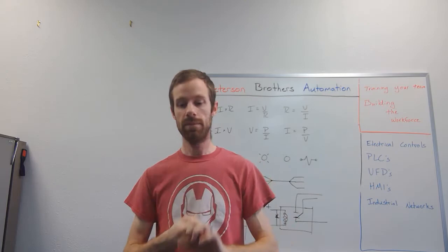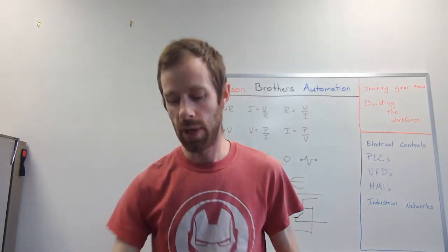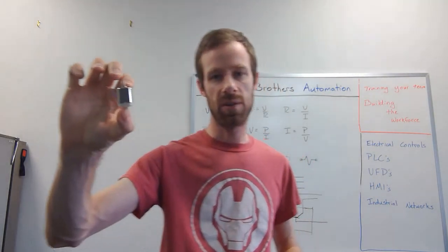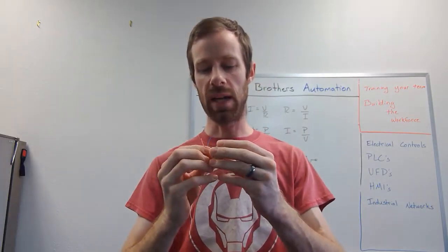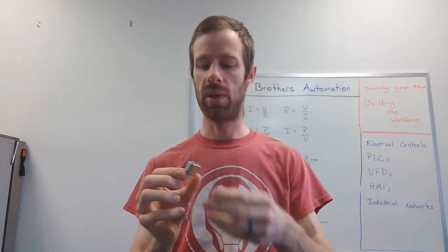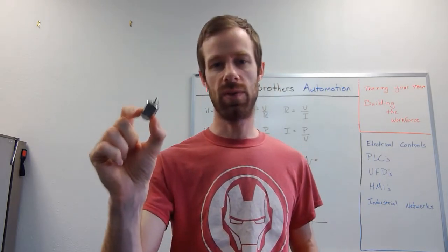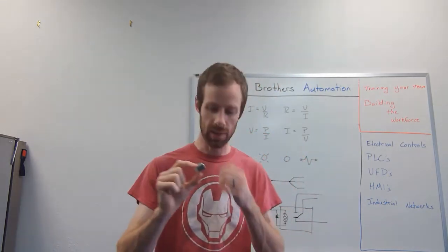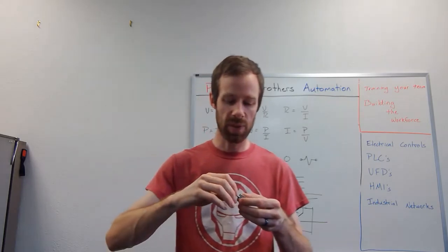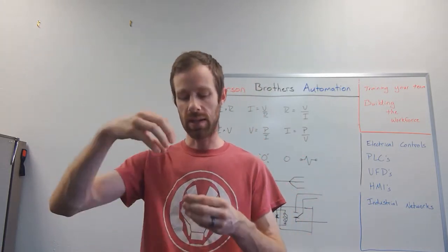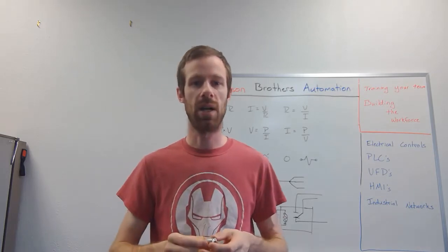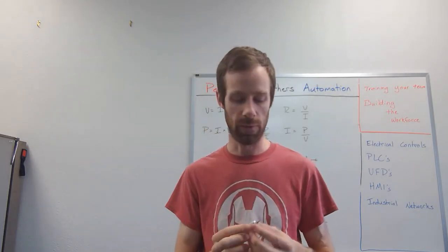Motion is another one. Motors come in all shapes and sizes. Here's an example of a little hobby motor. There's a variety of voltages that these little tiny motors can run on, commonly down to 3 volts all the way up to sometimes 12 or even higher. They spin extremely fast, but they're pretty weak. So if you plan on using them for anything useful, then sometimes you've got to install a little gear reduction system on them to make it go slower, but with a little more force.